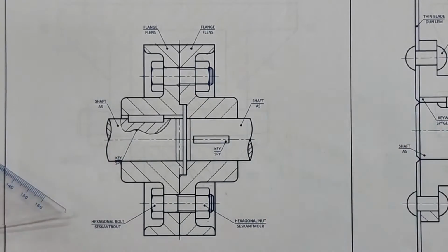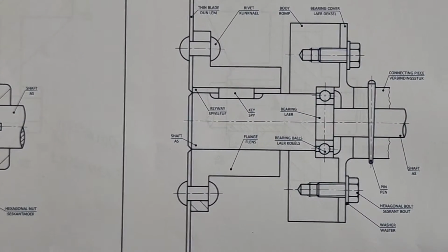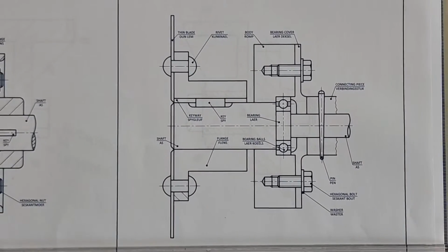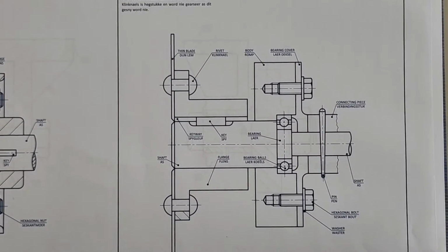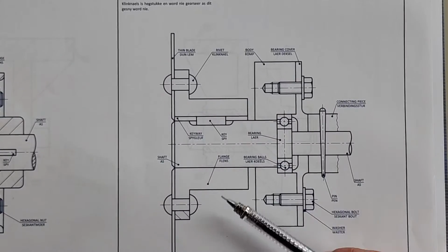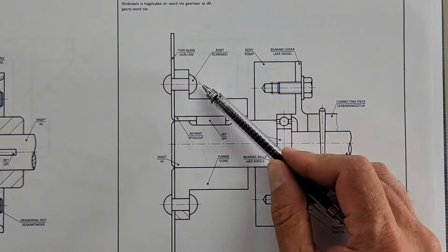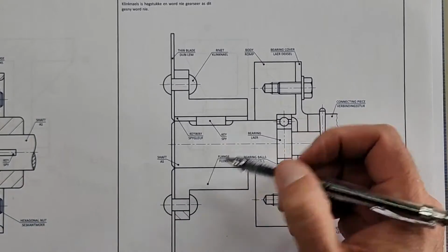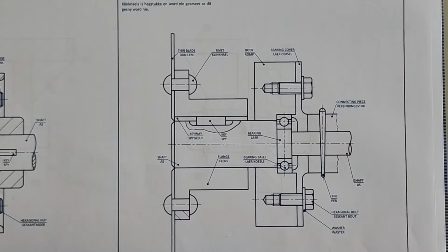Okay, alright, the last one for this lesson is on the right hand side. This is a bit bigger drawing. Let me just zoom out a bit for that one. Alright, let's have a look here. So rivets are fasteners and are not hatched when sectioned. They actually tell you that here on top. So here's a rivet. There's another rivet. There's a key. So immediately when I see a key, I know there's going to be a partial section.